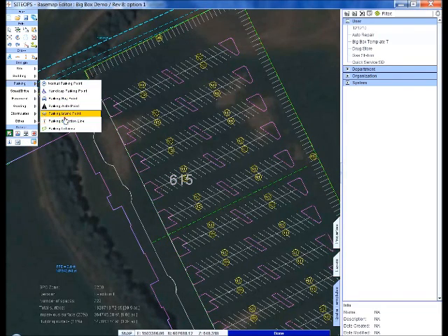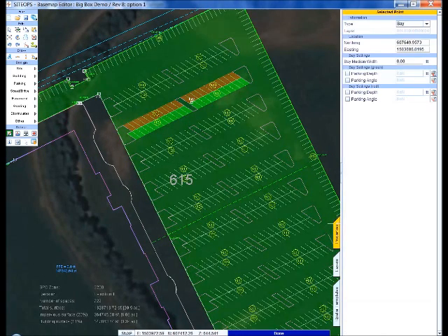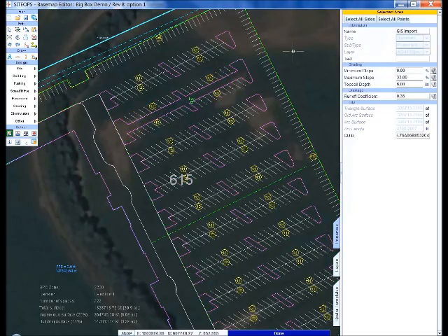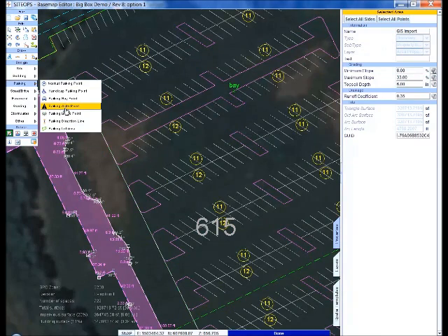Let's add, for example, some parking features. Let's add a parking bay point. Again, just simply click on it, change the property, and there we go. Now we've got landscaping, bioswale, any kind of thing we'd want to add in there. Let's add something as simple as handicap.